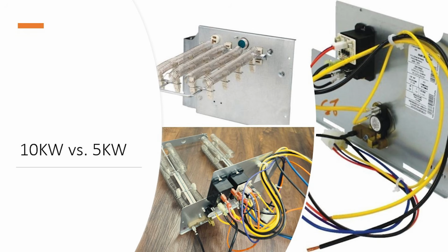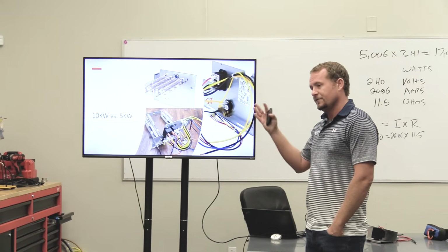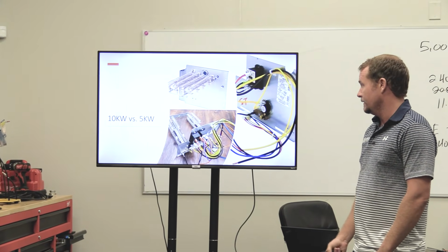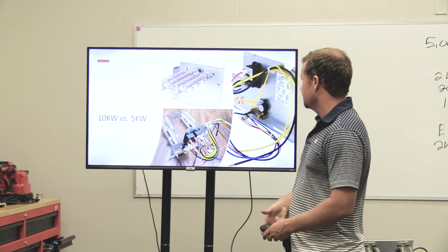And this is just showing this. So if you look here, you can take an amp draw on both wires at once, as long as you're not on opposite phases. If they're on the same phase, then you'll measure the same. And if you took both blacks and put a clamp over both, you'd measure the cumulative amount.